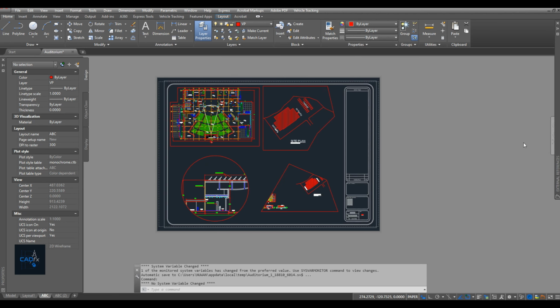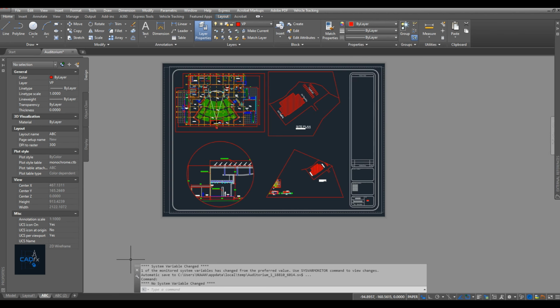You can also do this with a shortcut. If you just want to move a layout, simply click and drag the Layout tab to the position you want. And if you want to copy it, hold down the Control key while you click and drag the tab. You can see how that allows you to manage your pages in a simple and efficient way.